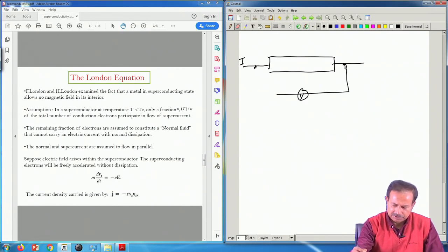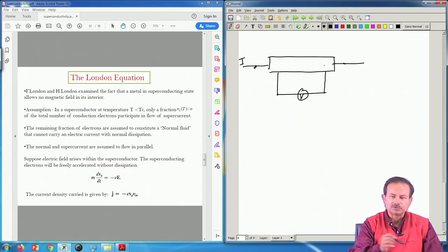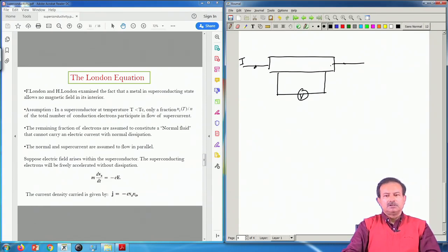Instead of measuring the current and voltage at the same lead, one measures current and voltage at 2 different leads. You find out the voltage drop across these 2 leads, and then you know the current that is flowing, and so you know the resistance between the 2 leads.